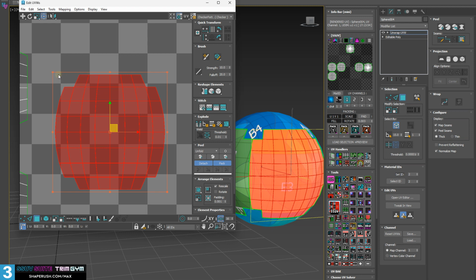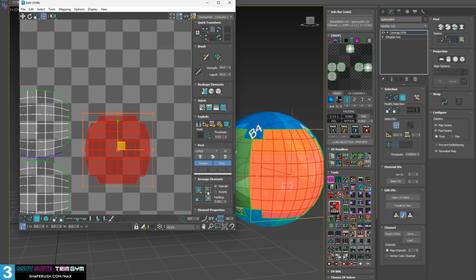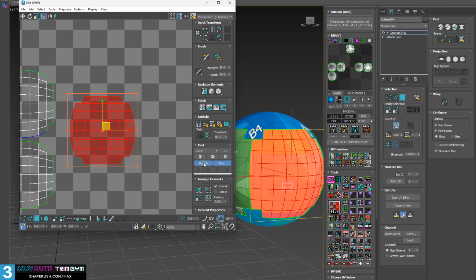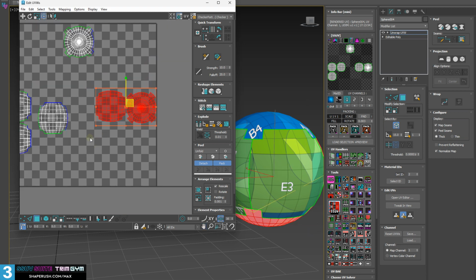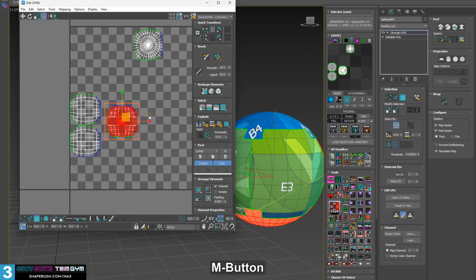It's actually where it would have its most left vert, most top vert, most right vert, most bottom vert. You get the idea. Okay. So now that the coordinates have been set by left clicking to define that space, I can then select other elements. Okay. And right click. That will place those elements onto that location.